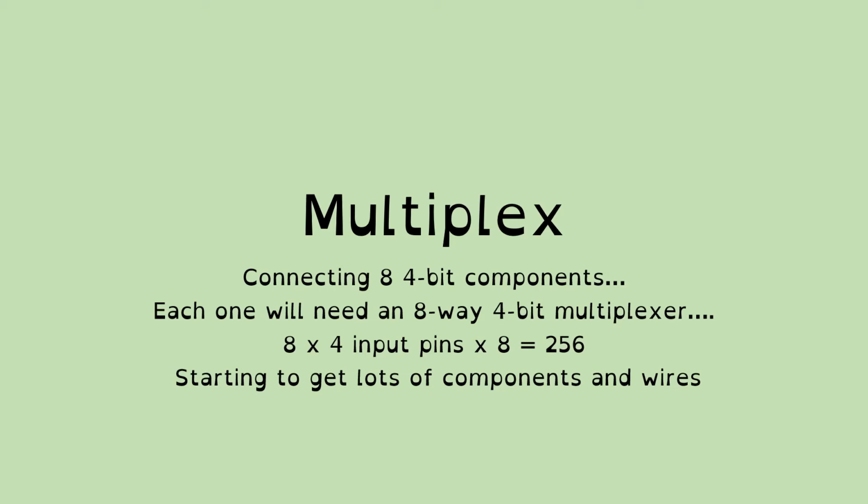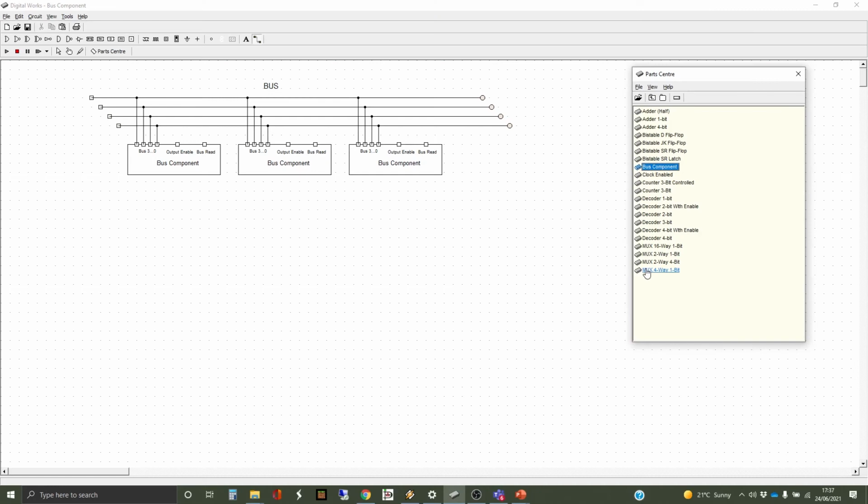So there is another way of doing interconnectivity. Multiplexers are useful, and we will use them in the long scheme of things in the CPU that I'm creating. But I'm going to flick back to DigitalWorks, the digital simulation software, to show this. It's just a diagrammatical thing. It doesn't actually do anything active. It's just to show the principle, which is that instead of doing massive interconnectivity, in these situations you always use a thing called a bus.